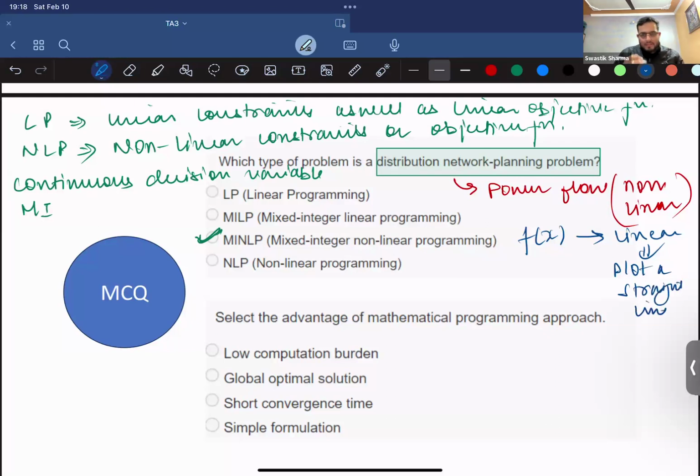So Dharmendra Kumar, if I say a system is y equals 2x plus 1, will it be a linear system or a non-linear system? It's a linear function, but it will be a non-linear system, right? 2x plus a constant. Yeah, because it doesn't follow what principle? Homogeneity or what principle doesn't it follow? It doesn't follow both of them. So the linearity property is not there. It doesn't follow homogeneity. So that system is not linear.